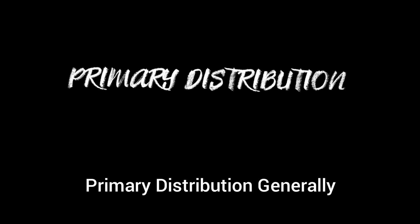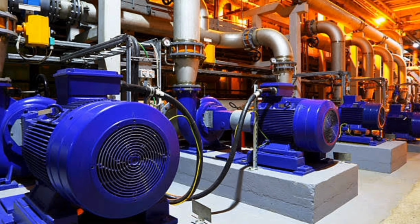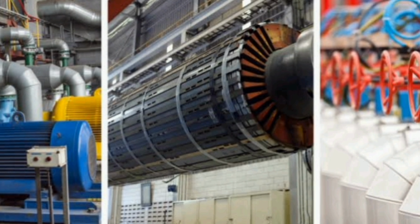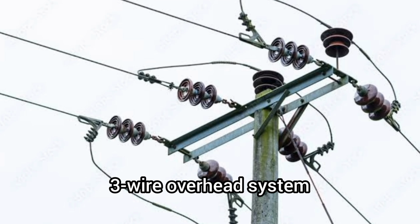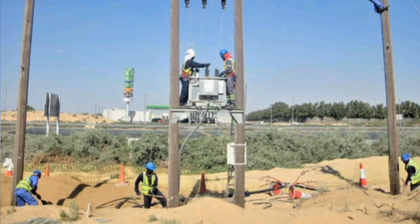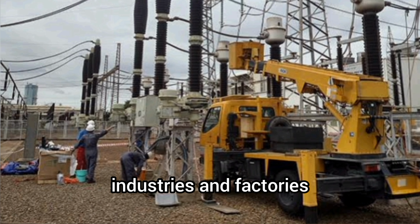Primary distribution. Generally, electric supply is provided to those heavy load consumers, commercial power supply for industries, where the demand is 11 kilovolt, from the lines which carry 11 kilovolt in a three-phase, three-wire overhead system. And they make a separate substation to control and utilize the heavy power in industries and factories.